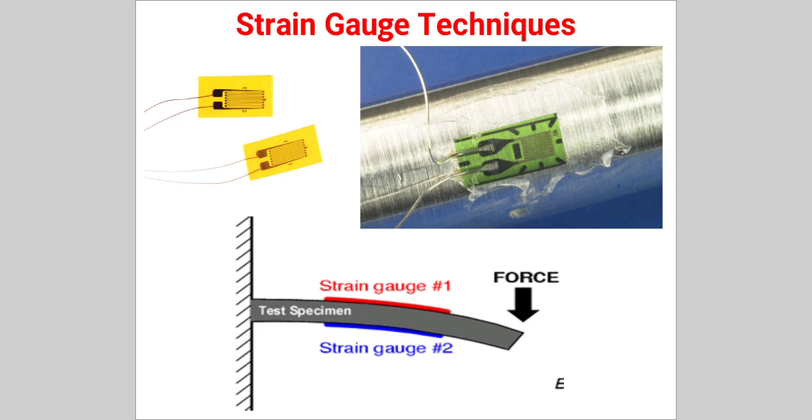As we know, the basic working principle of the strain gauge is that the change in resistance is directly proportional to the unknown parameter. The strain gauge has a standard resistance of 350 ohm, 1000 ohm, etc. So if the strain gauge comes in contact with any moving part, its resistance will change. For example, from 350 it becomes 450, from 1000 it becomes 1200.